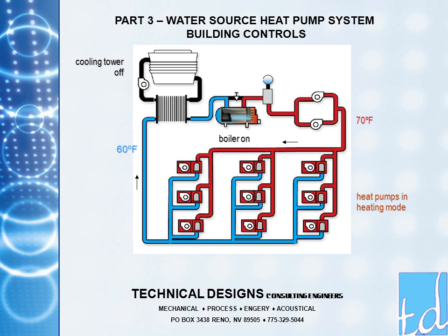In many buildings, the temperature set point of the space thermostat is set back during unoccupied hours in the winter. For example, the space temperature is controlled to 68 degrees during the day, but allowed to decrease to 60 degrees overnight. This practice is called night setback. While it saves energy during unoccupied periods, night setback imposes an additional heating load on the system when the set point is reset back to 68 degrees. This is called morning warm-up.